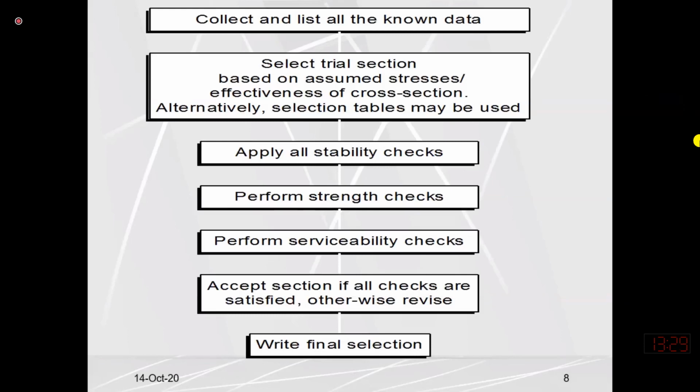And the next information is that I am going to design this beam of steel. So steel means what strength of steel is available in the market. Second, I have to consider what type of end condition I have to use. If you are considering the simply supported condition, then during execution you have to design a simply supported connection. If you are considering the fixed-ended beam, your analysis will change accordingly, and during the construction phase we have to provide the moment resisting connection.